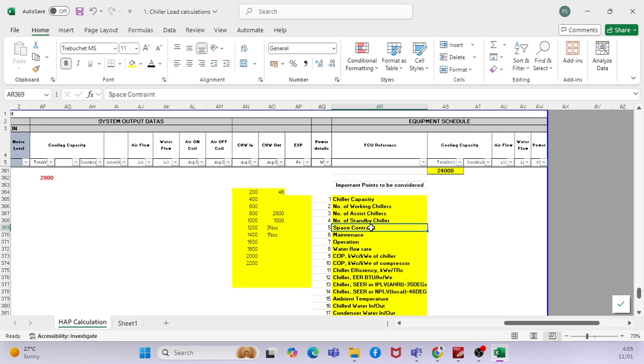Can I ask you one question, if that's okay? Yeah, you can ask. So this chiller capacity, I know you're trying to say is at 100% load, right? But 100% load is not always the scenario, though, right? Yeah, but you have to select for 100 percent, right? You will have a scenario where you have 100 percent. So at that time your chiller should support the 100 percent requirement.